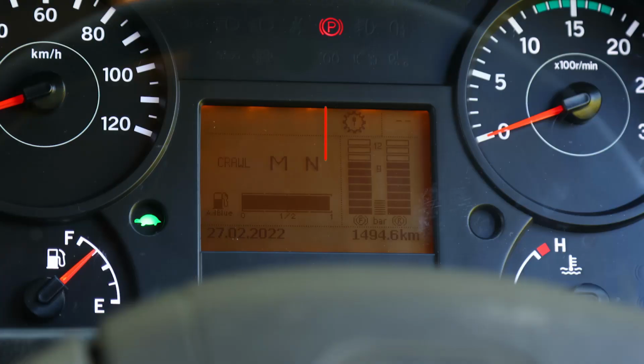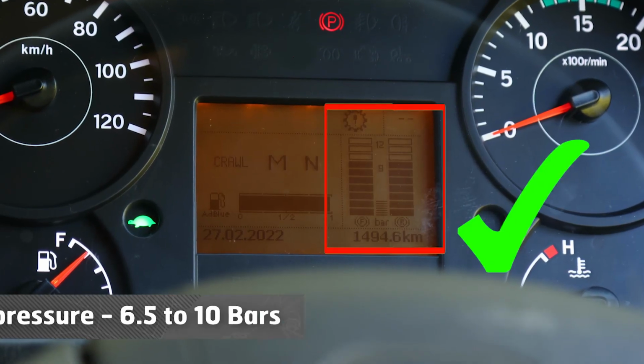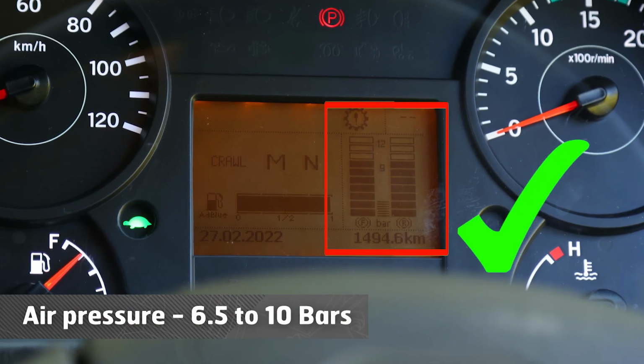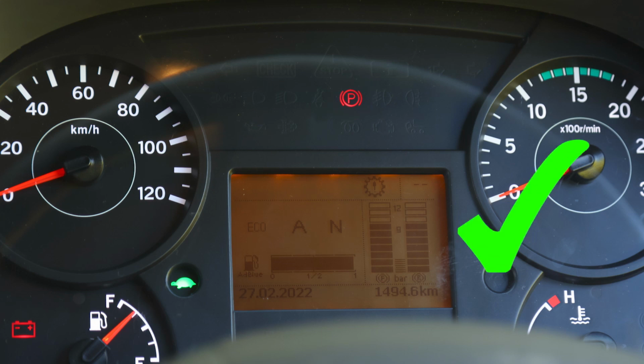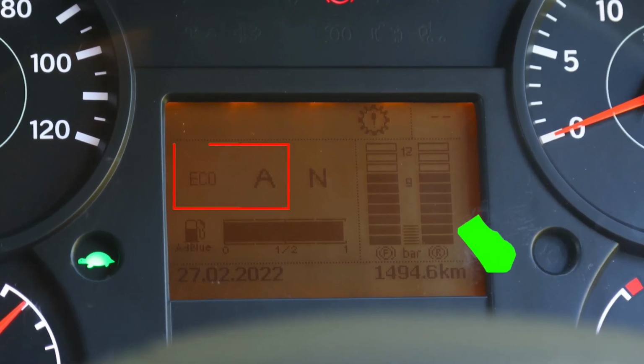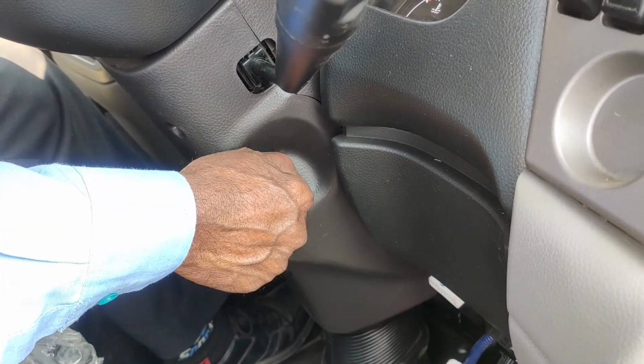Ensure pneumatic pressure is 6.5 to 10 bars. Watch for warning lights glowing on the instrument cluster and ensure N is displayed on the cluster. By default, the vehicle will be in auto mode and eco mode. Start the vehicle.